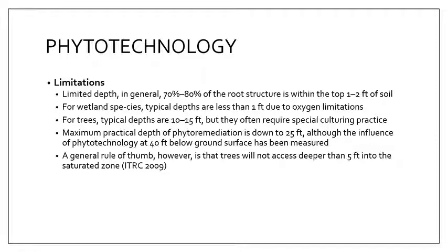Now, the limitation of phytotechnology is that you have a limited depth. Typically, the maximum depth that was ever reached by phytotechnology is 40 feet or 15 meters. Although the practical limit, or the general rule of thumb, is that trees will not go beyond 5 feet into the saturated zone.